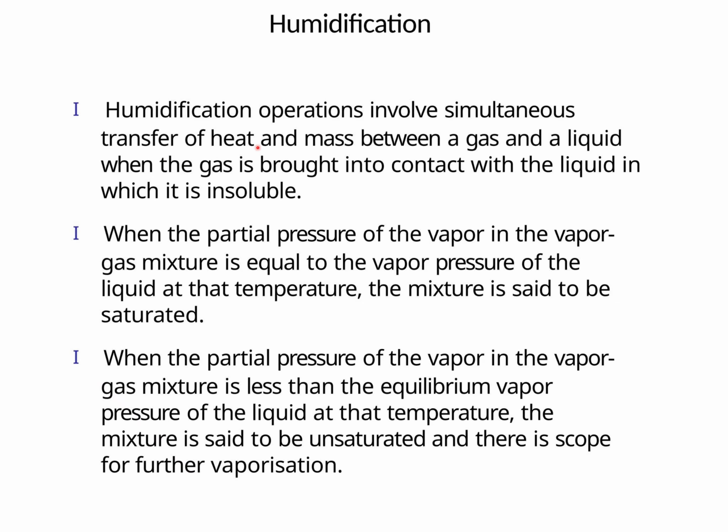Now let's learn humidification. It is usually the presence of moisture in the air. The humidification operation involves simultaneous transfer of heat and mass between a gas and a liquid, where the gas is brought into contact with the liquid in which it is insoluble. When the partial pressure of the vapor in the vapor-gas mixture is equal to the vapor pressure of the liquid at the temperature, the mixture is said to be saturated.